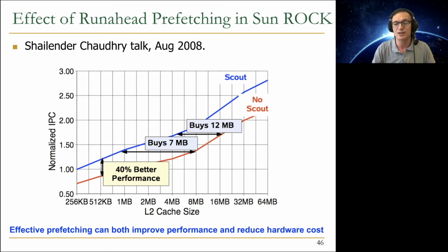If you keep increasing your cache size, you may not be utilizing your cache really well because it's a really reactive approach, and you may not be able to get all of the access patterns in your cache. But if you actually have a prefetcher, you can have a much smaller cache, basically. That's the key takeaway. So it's important to keep in mind that you can optimize the memory hierarchy intelligently if you have a really good prefetcher.